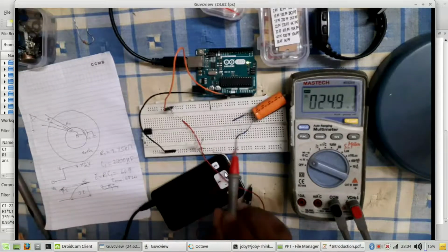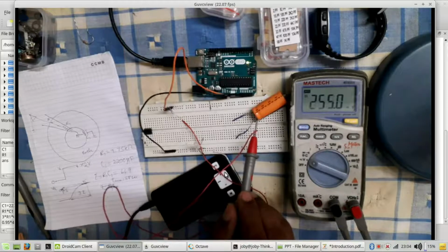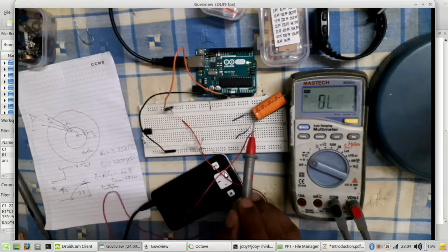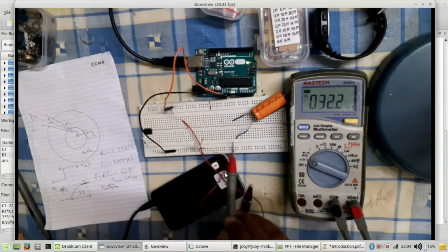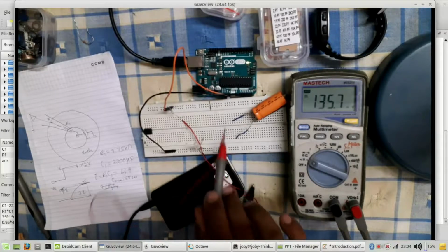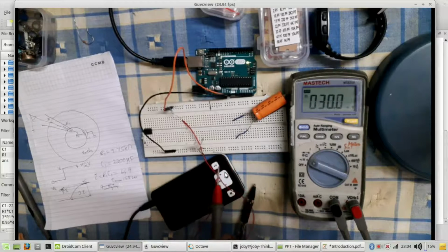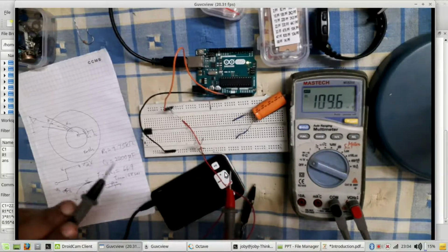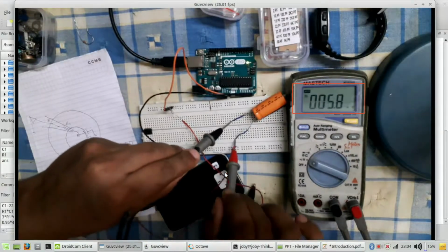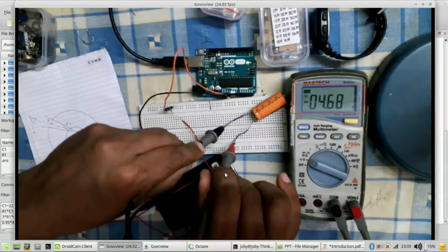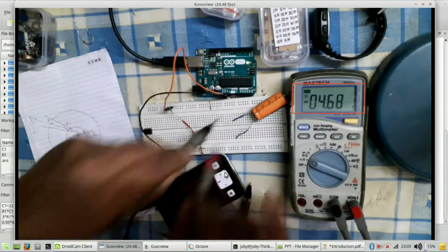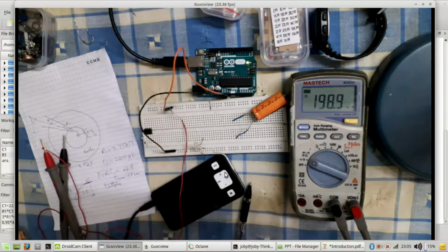Now this is the capacitor that we have charged. So according to theory, this capacitor should be now storing that charge. Now say I have not connected any elements to the leads, it is simply connected to these breadboard points. So if I measure the voltage across the capacitor, we should see around 4.7, which was the output voltage from the Arduino, right? So at least without any load, it has maintained the charge near 4.7. Now, can we use that charge to drive some device?